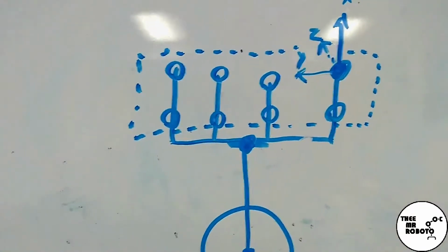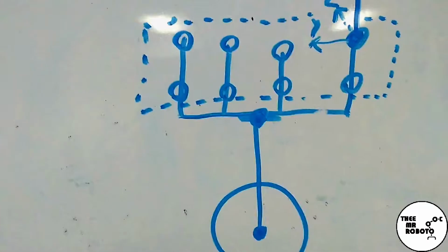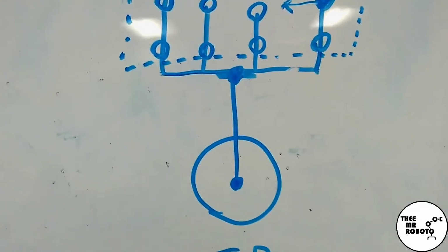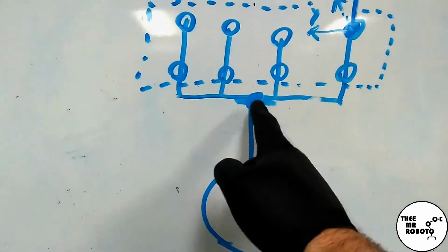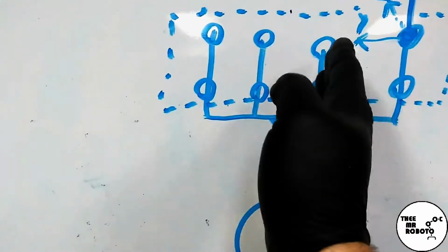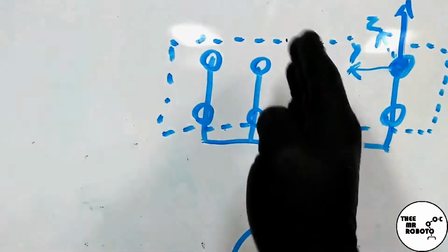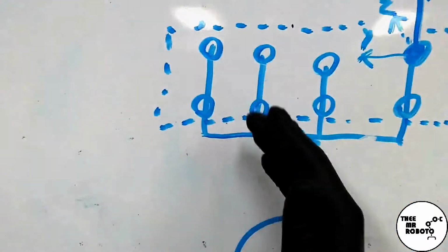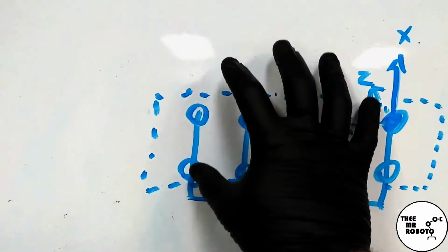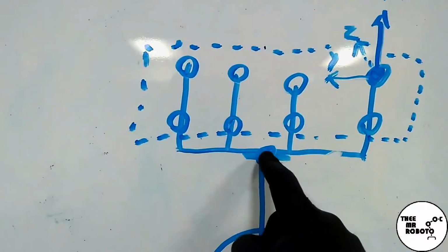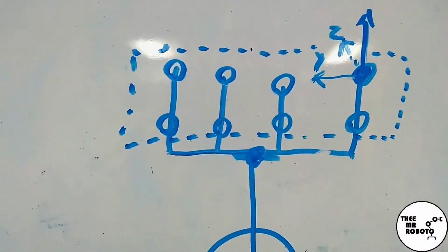When you're programming your robot, you have the ability to rotate around your different coordinate systems, okay? So if we were looking at the flange coordinate system like this, if we wanted to rotate this sheet in this direction, okay, this way, we could rotate around the z-axis, and that whole sheet is going to translate like this with an origin here, okay?